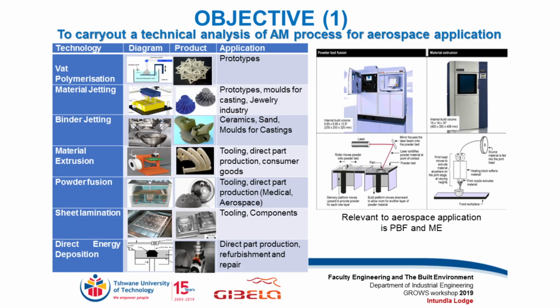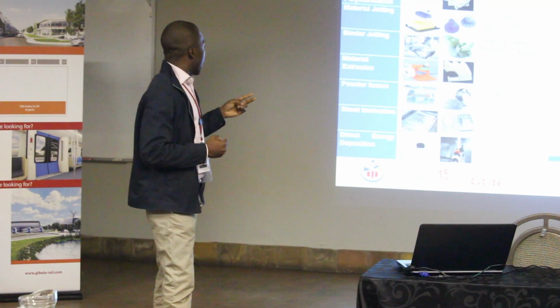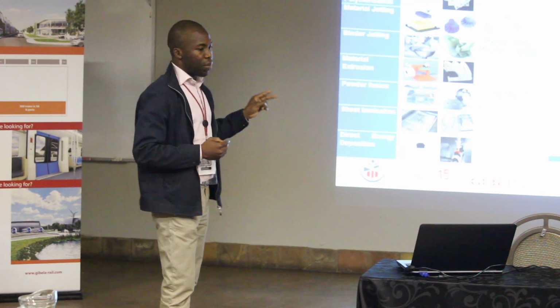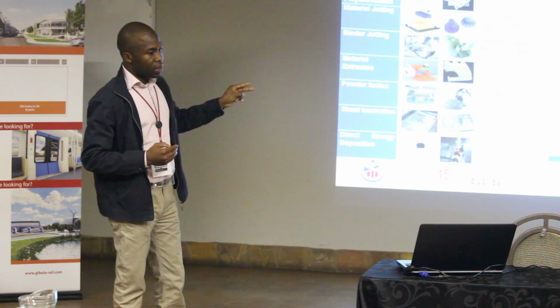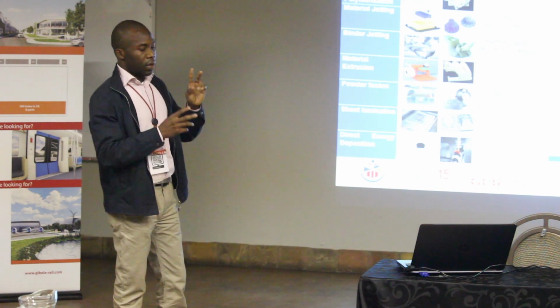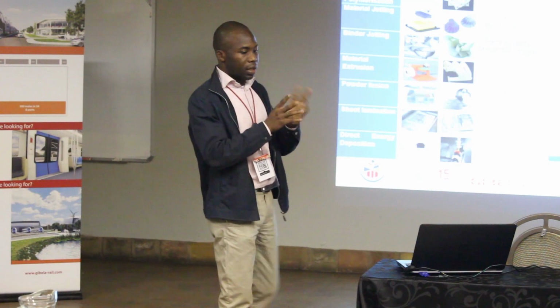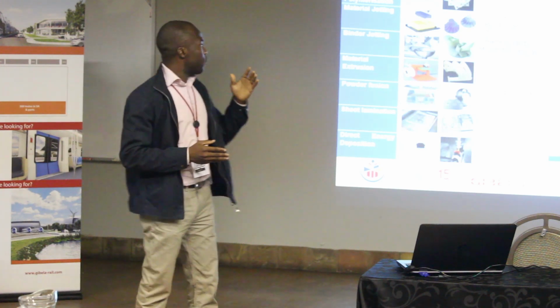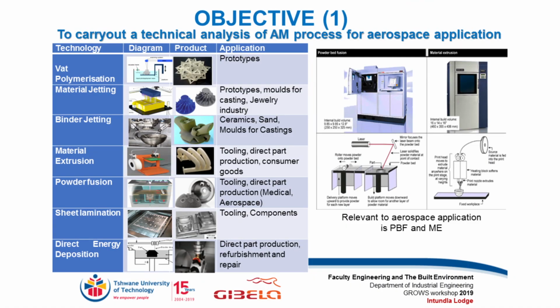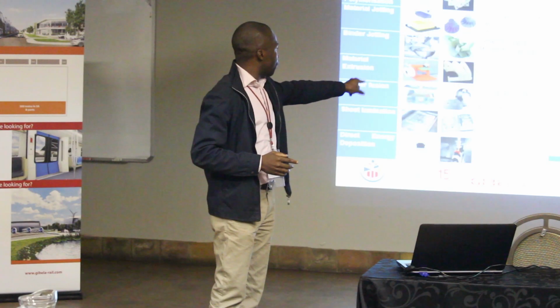Firstly, for the first objective, I looked into carrying out a technical analysis. There are about 7 production system techniques under additive manufacturing itself, but I looked at the ones relevant to aerospace application. So I discovered what is called powder bed fusion and what's called material extrusion. There are 2 techniques: one for polymer and one for metallic. The consideration here is for metallic, which led to the discovery of powder bed fusion.